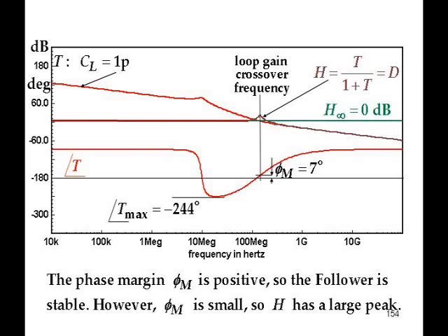And look what the phase does in between. Real gyrations there. It starts out at -90 because of the single slope. And then because of the additional double pole it encounters, it plummets down to almost 270. But then the zeros start bringing it back. And the two zeros bring it back to -90 degrees at infinite frequency.